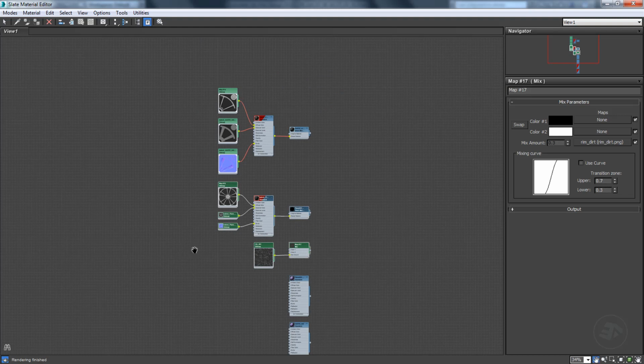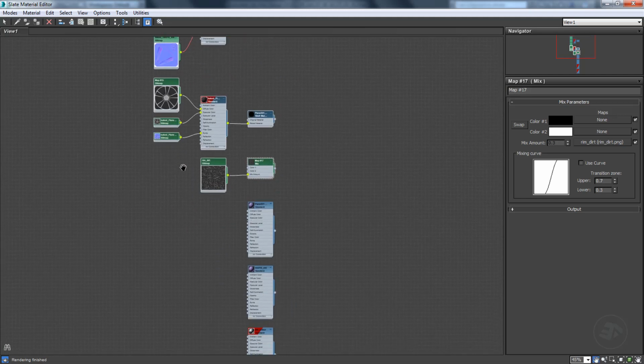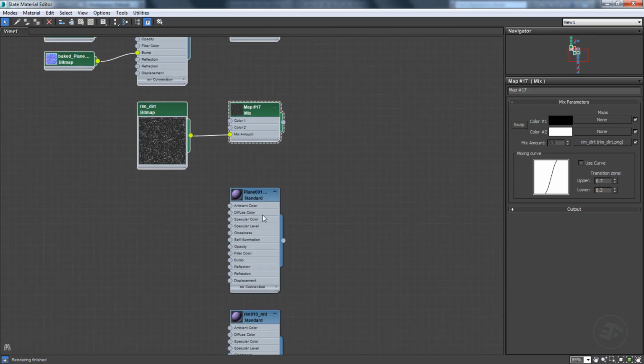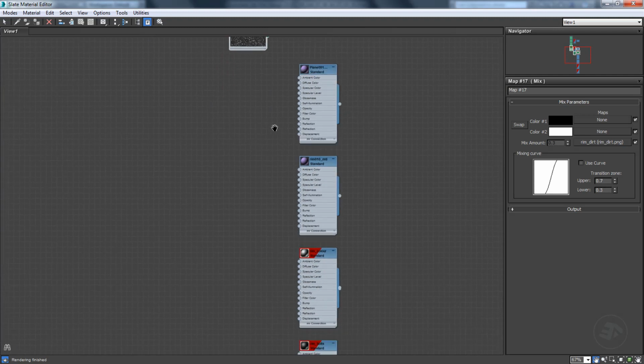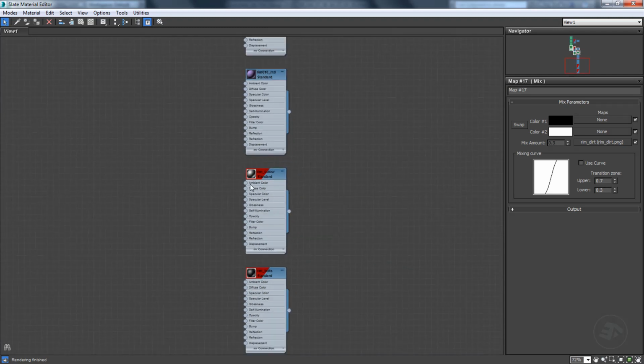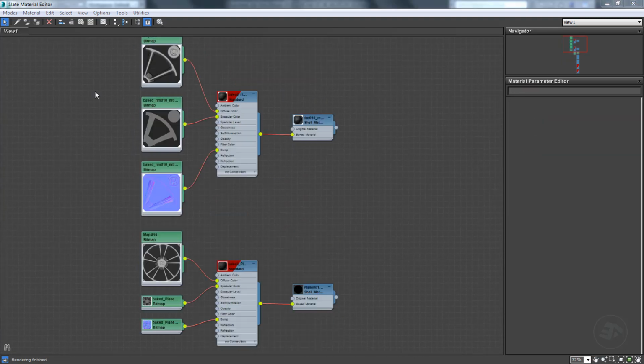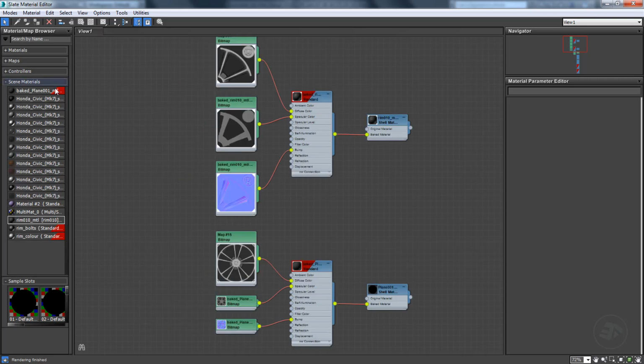It is always a good idea to keep only the active materials that you need in the viewport and delete the inactive. This will not delete the materials already assigned to any object. You can recall them any time by pick material from object or from the left side menu of the material editor.